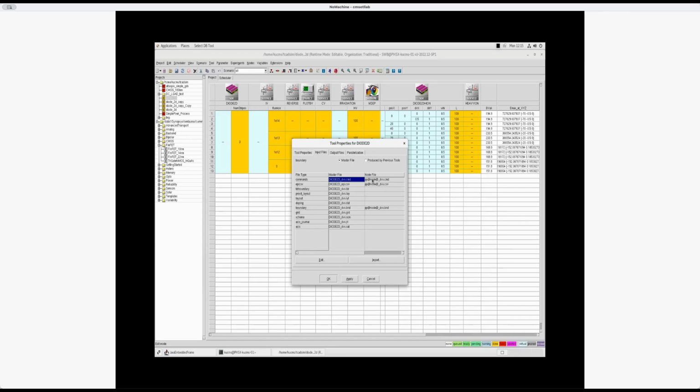You can tell it that it will take a file, and this keyword here, node, essentially tells the tool to look at the previous node in the hierarchy, to go back in time and look for the previous node attached to that process. So, for example, if you make a device, and then in the second step, which is going to be the device simulation, we have four different simulations. They all link to this parent node here. So this will take the number of this node and replace it when executing the real simulation.